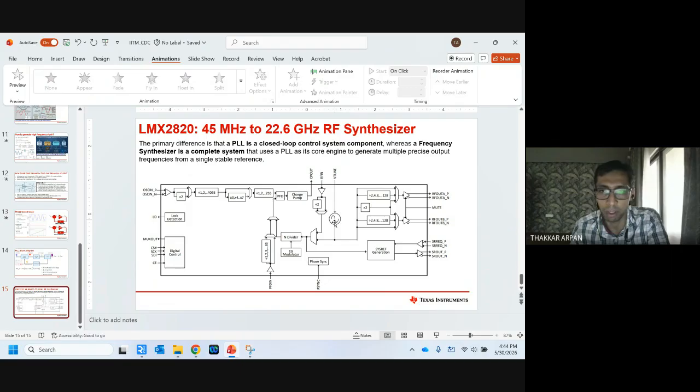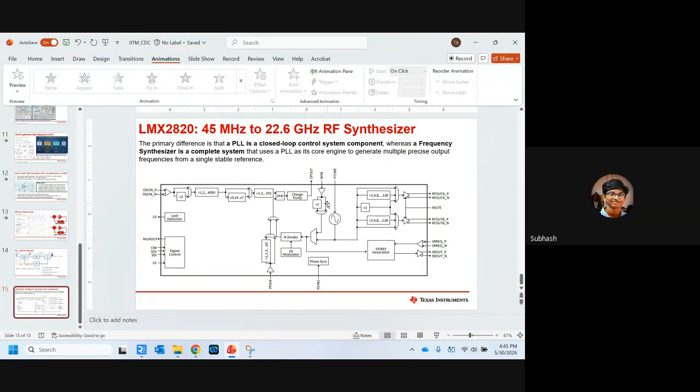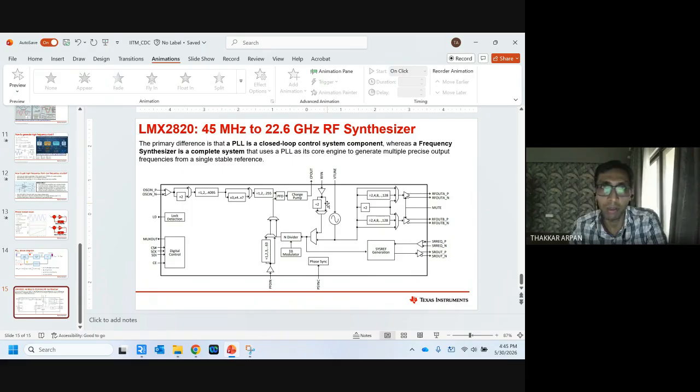But anyways, let's say we want to generate 11 gigahertz of signal here so that we can directly focus on the VCO. So this VCO I have to anyway make on chip. But the quality factor of these on-chip oscillators, whatever best you can make, will always be constrained by the metallization inside the wafers. Metallization inside the die or wafer, because it's like smaller components, its thickness and everything is going to be very limited. So the thinner the metals are, the more resistive they are going to be.